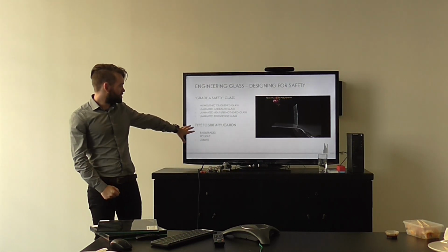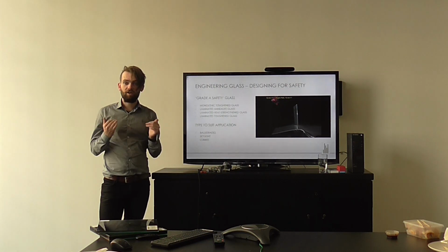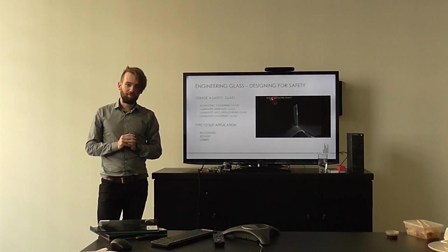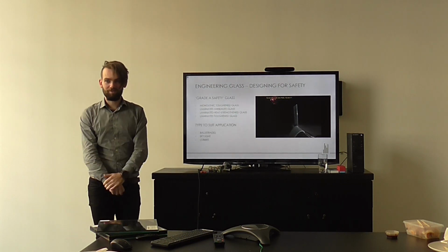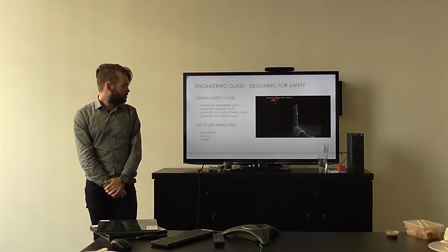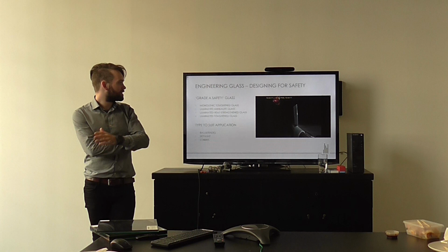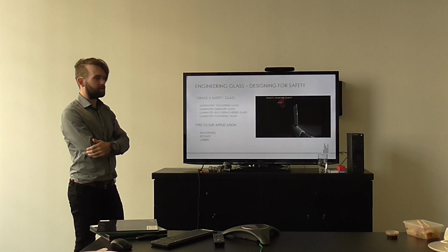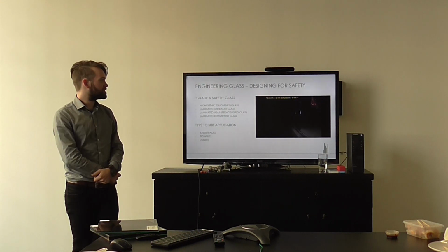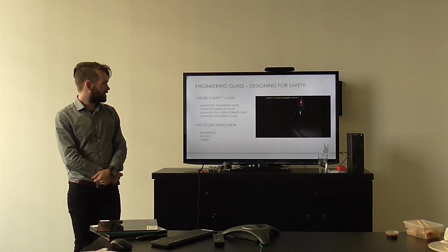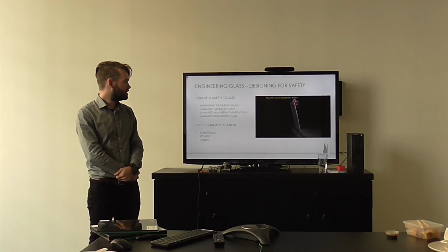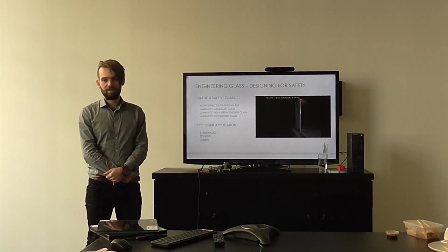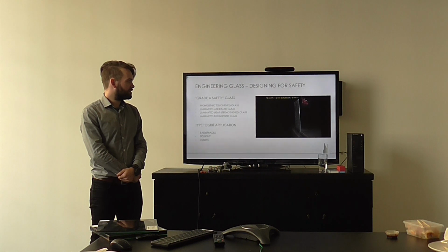And again, for the applications we're talking about here, in particular maybe the underside light of a skylight, if a piece of glass was to fall down on you, that may even be worse than just fragments of toughened glass breaking. And then the last one they show here is actually an SGP piece of glass, which touches back on what I spoke about earlier about the interlayer having some stiffness, in particular post-breaking. So as you can see here, it gives a good wallop. It breaks, but there's quite a bit of residual stiffness in the interlayer, at least in that glass product.